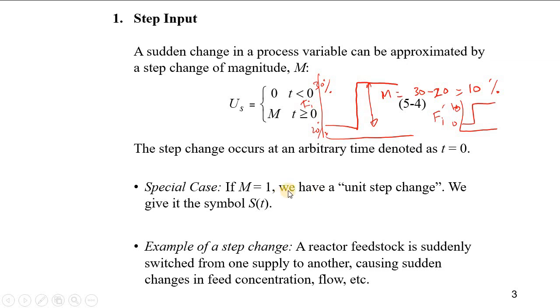Good? Very good. And if we stay in the problem, a very special case, it is just something that we bring in problems to make your life easier in the exam. Okay, so if we say a unit step change, what does that mean? It means a step change, and when it says unit, it just means that it is equal to 1. Okay, so my m is equal to 1. So if my m is equal to 1, then in the Laplace domain it is going to be 1 over s.